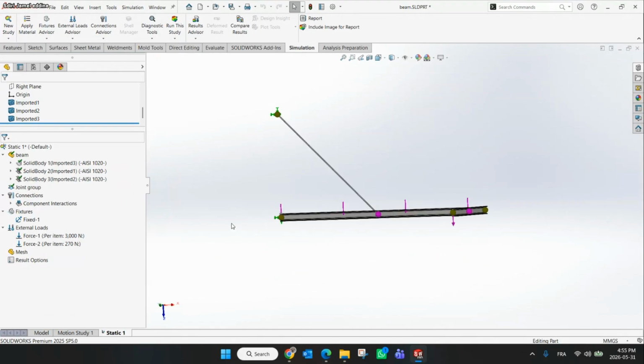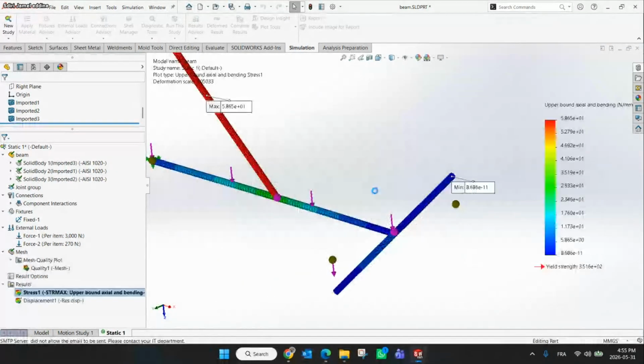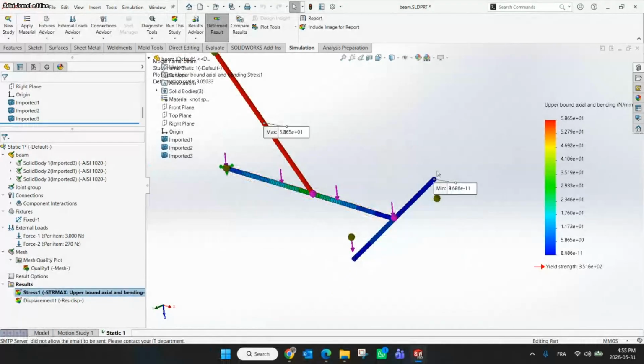For the beam type element, the mesh is a 1D mesh, one dimension. So it's only treated as a line. You will notice later when I run the study, they all are treated as a line. It doesn't take into regard their shape.